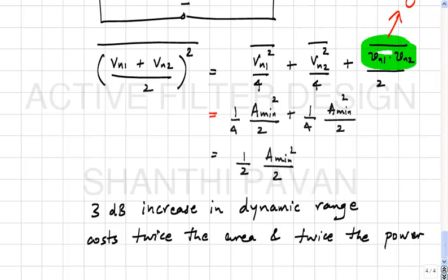All right, and this also gives you a way in which you can compare different filter designs. It's very likely that all filters that have ever been designed are targeted to a particular dynamic range. In some applications, for example, a 40 dB dynamic range may be sufficient. In several other systems, a dynamic range of 90 dB is perhaps what you need.